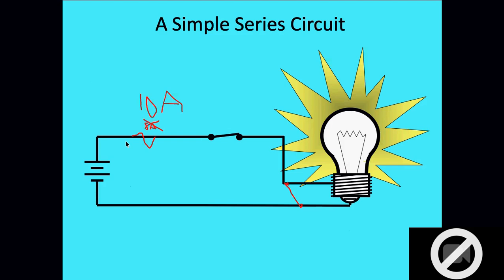We don't want to increase fuses in HVAC equipment and on HVAC circuits. And again, I'm going to speak from the not wanting to be an electrician standpoint. I don't want to increase amperage and fuses on line voltage circuits either, because we don't know the size of the wire.